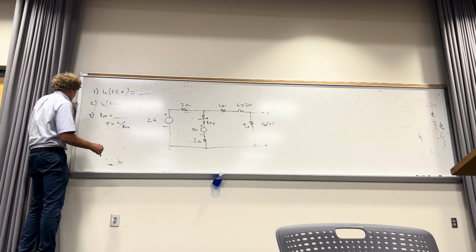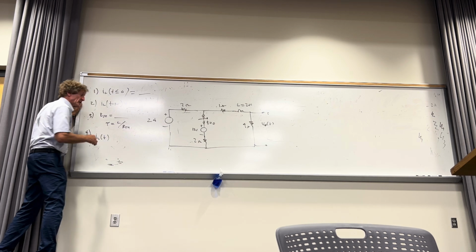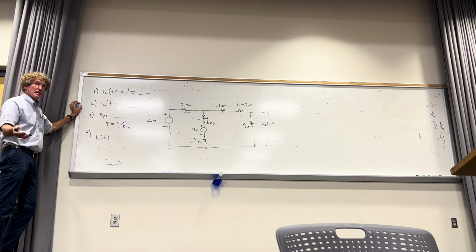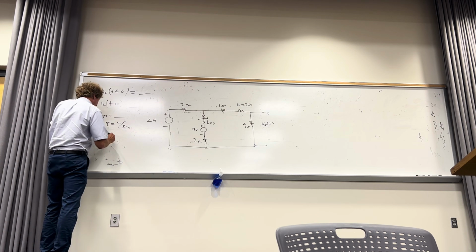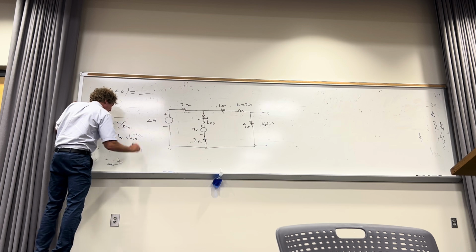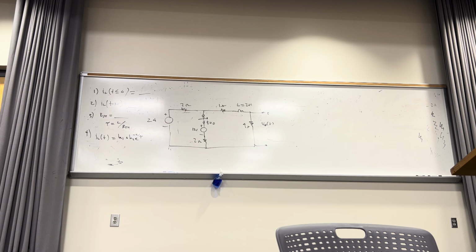Spend time. Finally, the fourth thing is you put the thing together. You say I_L is a function of t. We only care for t greater than 0; less than 0 is usually not of interest. I might ask for it. Obviously, you need it, right? But it's going to be equal to some constant, I can call it K1, plus K2 e to the minus t over tau. I want to just spend a moment and ask you a question. Remember, this is the current through the inductor. What is the K1, can you all see it in the back, by the way? The K1, what does that represent in your own words?